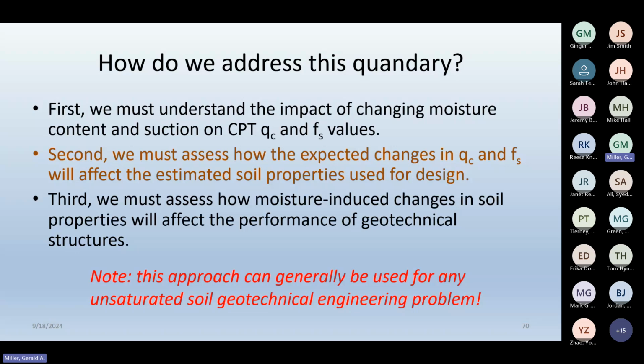All right, and so we're going to use the same approach. First, we want to understand how significant these changes can be. So we're going to look at some data that I've collected as well as others that relate tip resistance to moisture content or suction. And then we're going to look at how expected changes in QC and FS due to changes in moisture content affect our estimate of soil properties, and then how those changes in soil properties may affect our analysis of various geotechnical structures.